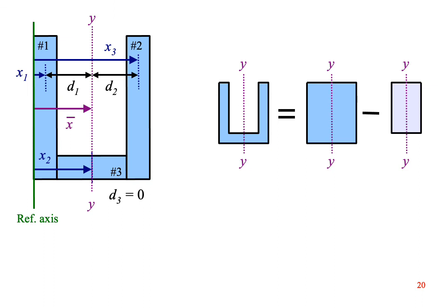What about I sub y? You have two choices with this shape. Either follow the 10 easy steps and solve the transfer formula the same way as before, but turn 90 degrees, or you can notice that the shape is symmetrical about the y axis. You can solve it faster by subtracting the little rectangle from the big rectangle because both rectangles share the same y neutral axis.